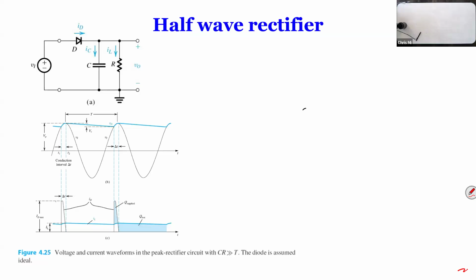And we said, depending on the size of the capacitor, if the capacitor is very big, the line drop is kind of a little flat. But if the capacitor is very small and the resistor also has small ohms, then it might actually drop quite dramatically. It might actually drop to zero before the next cycle starts.